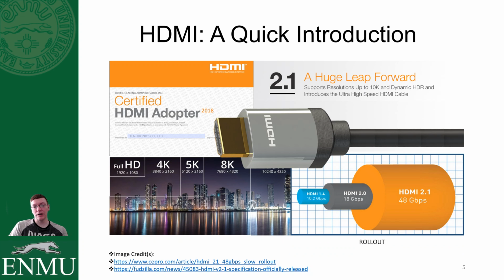And of course, with the evolution of the different standards from HDMI, we have been seeing constant increases in the data throughput. Back at 1.4 was 10.2 gigabits per second. The most widely available standard that is implemented in devices on the market right now is the 18 gigabits per second HDMI 2.0. And right around the corner, we're going to start seeing some devices with really high-speed chipsets, system-on-a-chips, FPGAs, and that sort of thing that can pipe out data at 48 gigabits per second with HDMI 2.1.